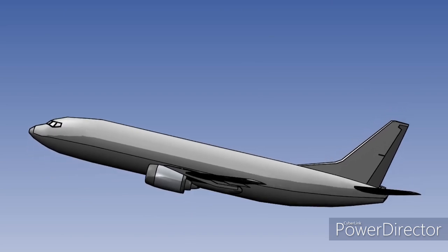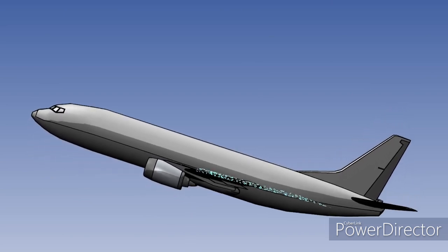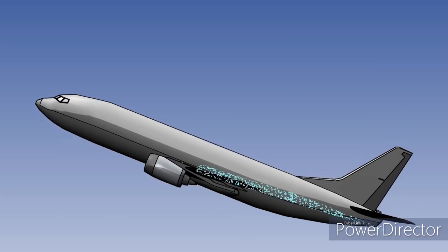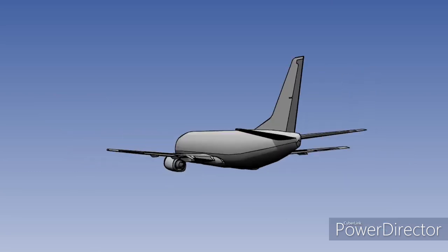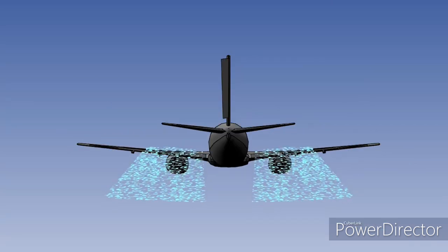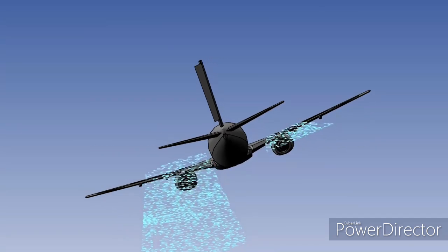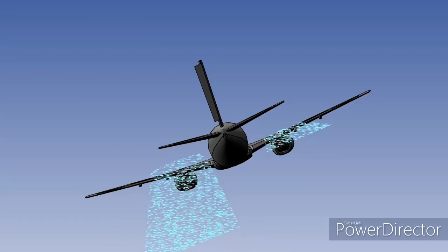Pilots should be careful not to pitch up too quickly, as this may restall the wing, even at a higher speed, which is known as a secondary stall and is covered in detail later in this series of lessons. The rudder should be used with great caution at any time when stalled or close to the stall, because of the possibility of causing a spin, on which more later. It is safer to use the rudder only after the wings are unstalled, and then only to prevent further yaw if a wing has dropped because it has stalled slightly before the other. It is generally safer only to use the ailerons to level the wings, also once the wings are unstalled.